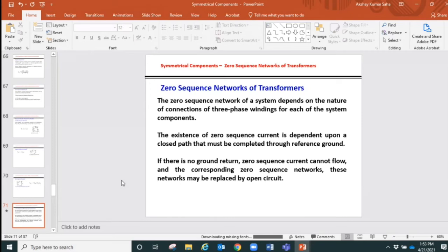We use isolators, like manual ones in olden days. Still they are there, those manual isolators. So we isolate them. The secondary side is open. And now what we need to do to fix that problem, we come and check and all those things. So when the problem is fixed, then we supply the primary. We still keep the secondary open.